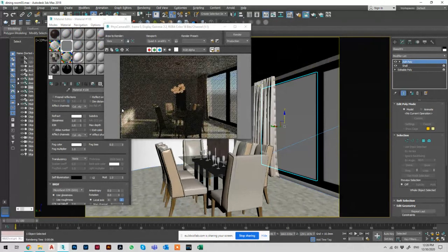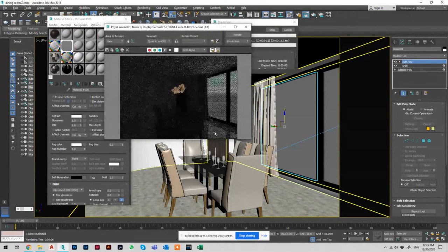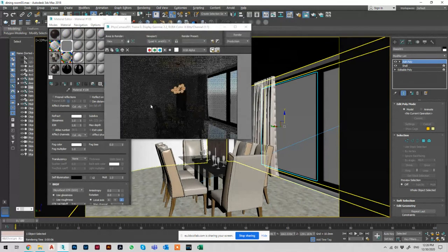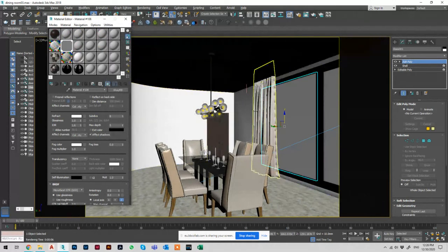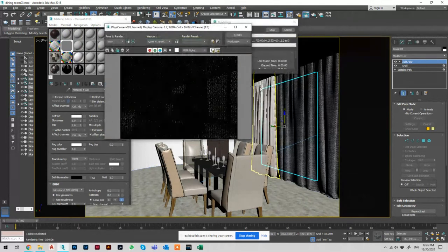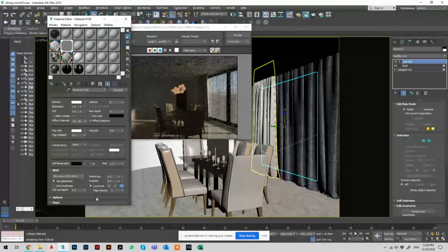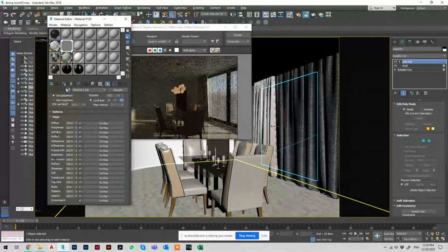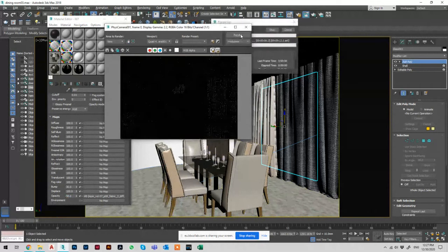If you add a glass material and then you have an issue of the sun not coming inside this way, for example, what you can do is you can just make sure that you select the material and then click on Effect Shadow. Okay, so now this is much better. I thought that I had an issue with the material itself, but then it turns out that it's not the curtain, it's the window. And just change the opacity here, for example, to 50, and then that's it.